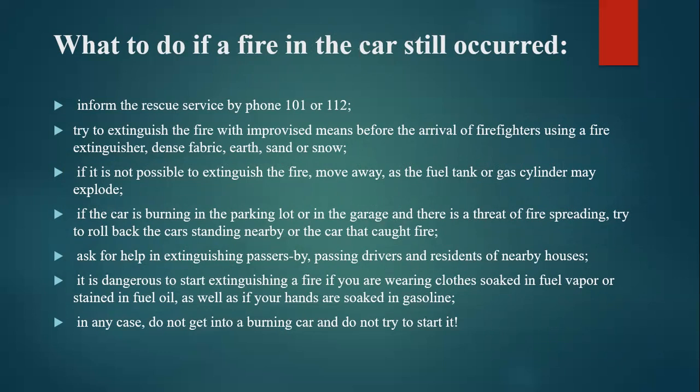If the car is burning in the parking lot or in the garage and there is a threat of fire spreading, try to roll back the car standing nearby or the car that caught fire. Ask passersby, passing drivers, and residents of nearby houses for help in extinguishing. It is dangerous to start extinguishing a fire if you are wearing clothes soaked in fuel, vapor, or stained in fuel oil, as well as if your hands are soaked in gasoline. In any case, do not get into a burning car and do not try to start it.